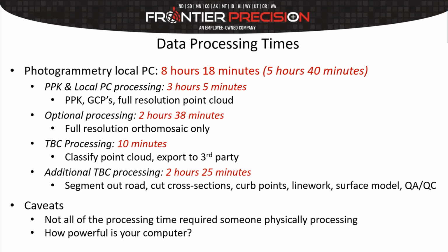What I mean by that is first we have to process the PPK data and process the photogrammetry. This includes processing the PPK from the cloud system, bringing it into the software and running the initial orientation on it, constraining it to the ground control, re-optimizing it, and then producing a full resolution point cloud. We decided to go with the full res point cloud just to have the density match up with what we would be seeing with the LIDAR sensor. That whole process took 3 hours and 5 minutes.